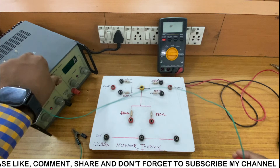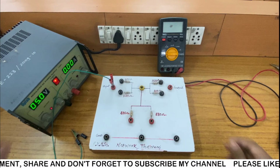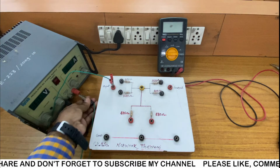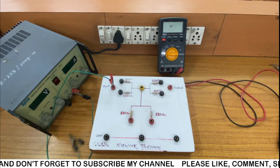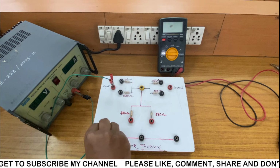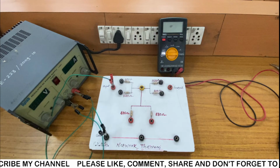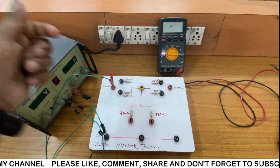This is the experiment setup. I have put the V1 as 5 volt. We are connecting it to the input. So same as the Thevenin theorem, we are going to perform this experiment. The only extension is that we are going to connect RL and we are going to vary the RL and measure the VL.